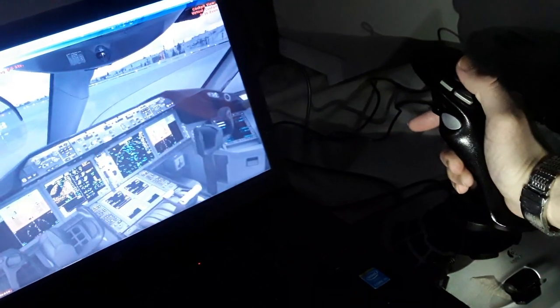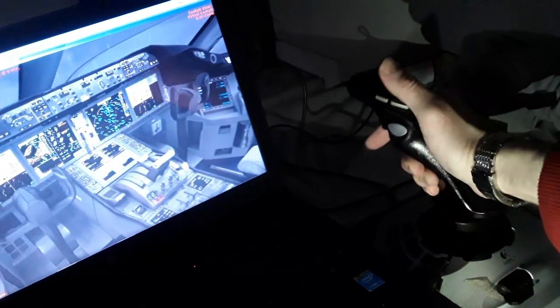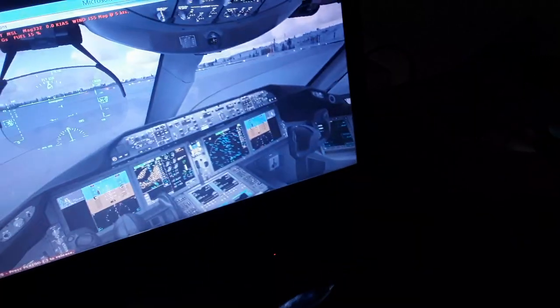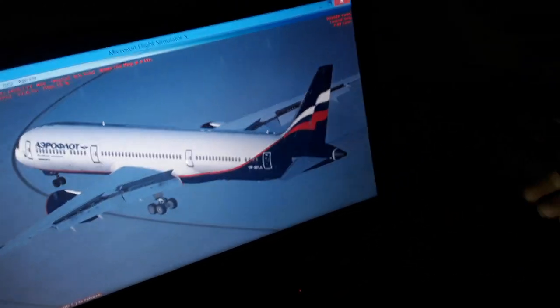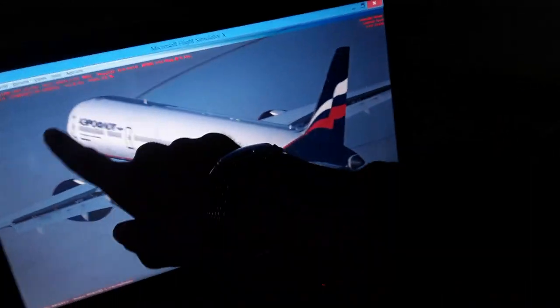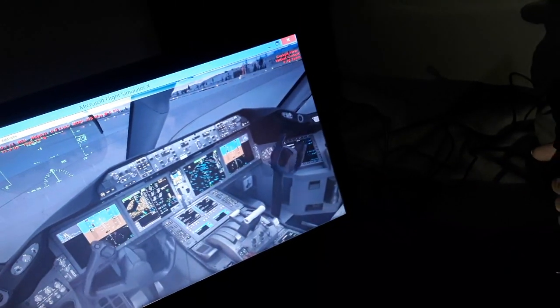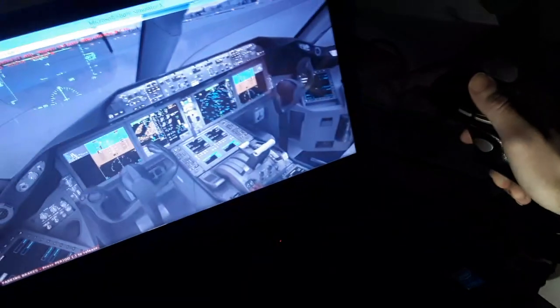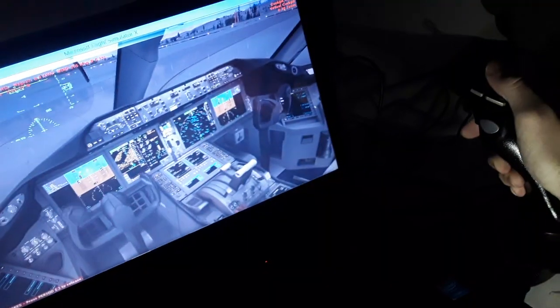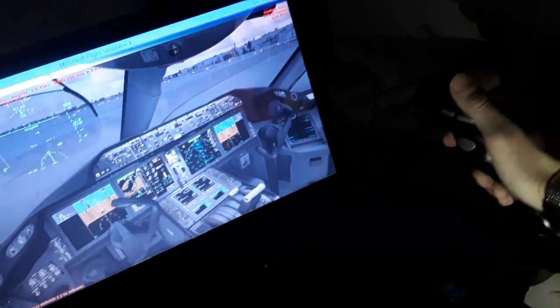So we have one more axis over here to see. So we see the yawing axis. And over here we also have the nose wheel. We have from the front nose to the tail the longitudinal axis, this axis. So this is the side stick left and right, the longitudinal axis in the Airbus. In the Boeing it is the control wheel left and right like this. You have also all flight controls together. And it's side stick left and side stick right in the Airbus, in the Boeing yoke control wheel left and right